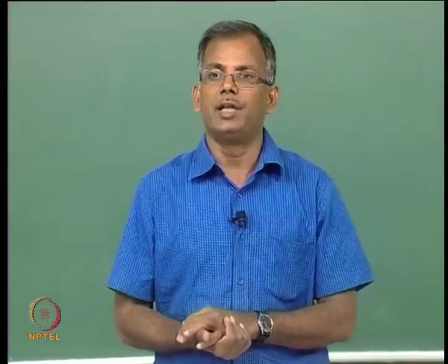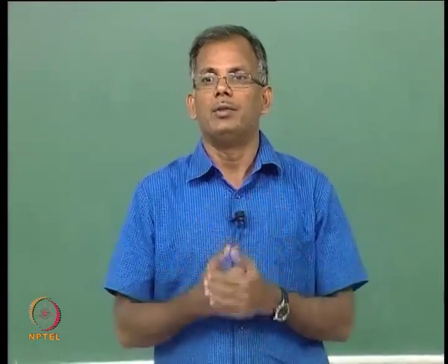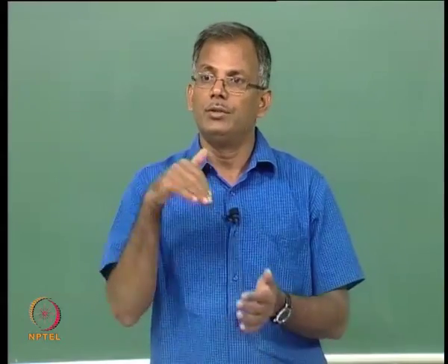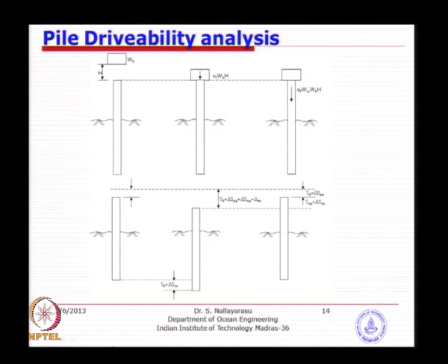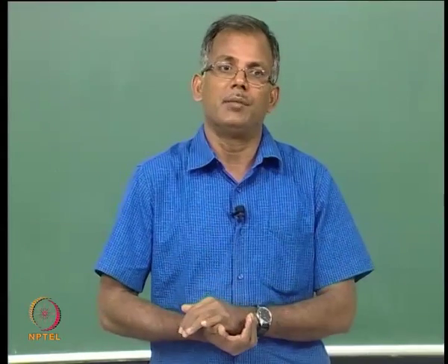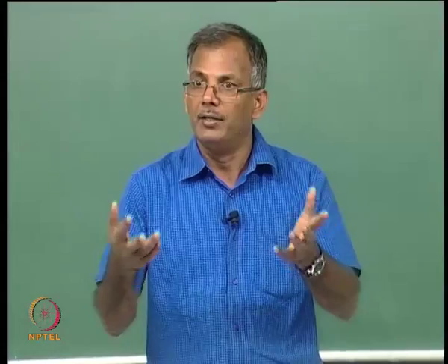If it is in the elastic stage, it is going to bounce back. So, in order for you to drive, you need to see the soil is failing, and then finally you have a set value which includes the elastic compression of the pile. We do not want the pile to go into plastic compression, that means the pile has failed, that means we can't use it.